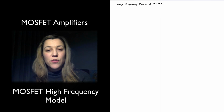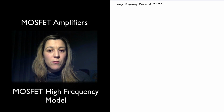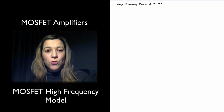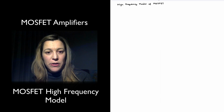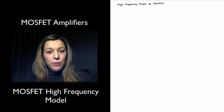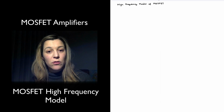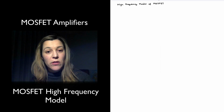Hello. In this video, we're going to talk about the high frequency model of the MOSFET, which is going to allow us to estimate the bandwidth of our amplifiers. We have talked about already the low cutoff frequency for MOSFET amplifiers, which, as we mentioned, is set by the coupling and bypass capacitors and the equivalent resistances connected to them.